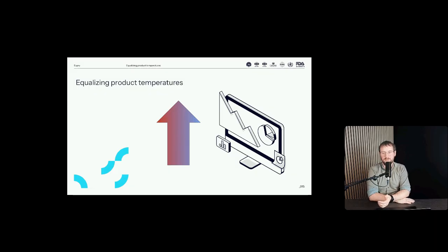And why is that the case? Well, there are different scenarios where that plays into a role. So the main concern when choosing a measurement frequency is basically if you measure too slowly, you'll miss a lot of the peaks and valleys of your data. Let's say we took it to this extreme and we would only measure once per hour. You could basically have opened a door, let in a lot of non-conformant air, and then close it again, and you would not get that information.